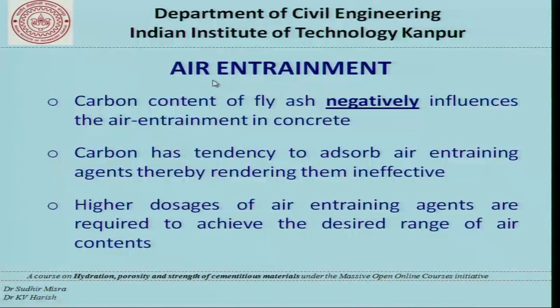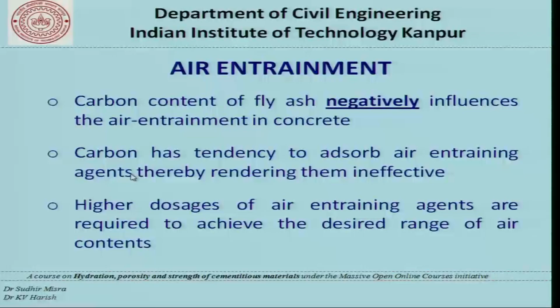Now, the other important property is air entrainment. Remember that air entrainment is primarily required only if there is a freezing and thawing environment. If you go back to the previous lecture where we discussed chemical admixtures, and in that we discussed air entraining admixtures, you find that entrained air is not present in concrete. You will have entrapped air voids, and you may also have capillary pores and gel pores. So, entrained air comes into picture only when you have an air entraining agent, and air entraining agents are used only when concretes are subjected to freezing and thawing, because you need additional air in the mixture in order to resist the expansion and contraction of ice crystals inside the concrete. So, all these things you may have to recall when you read this slide back.